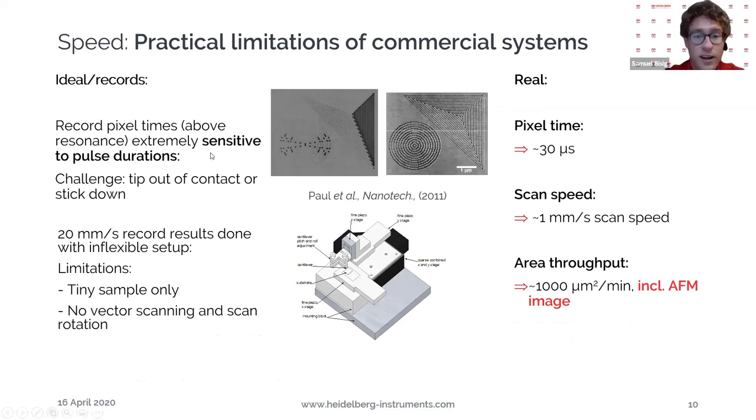If you're operating over the resonance frequency, you are very sensitive to the actual pulse durations. And this you can see here, if you compare the left to the right, how sensitive it is to just minor changes in the pulse duration. Either the tip sits too long at a certain time and removes too much material, or it doesn't pattern deep enough.